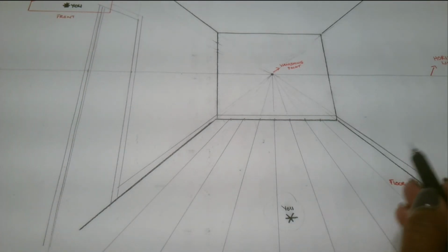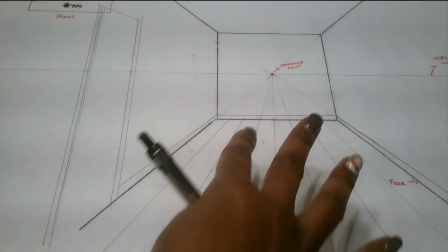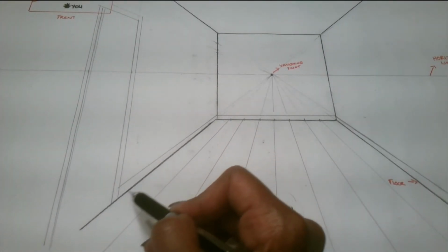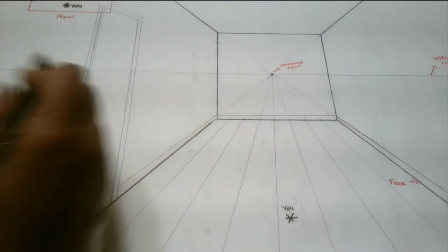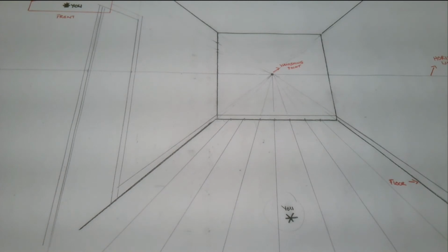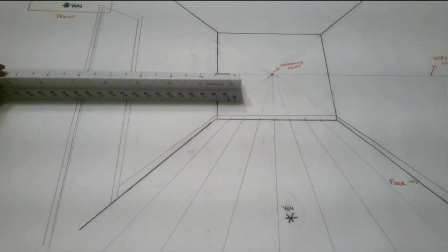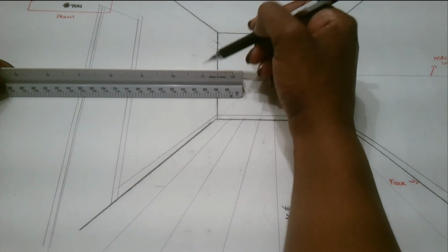If, for instance, you wanted to create tile flooring, you will go the same route as you did here, but how would you get these lines across? Would you measure here and just start drawing lines over? No, you would use your horizon line from up above. And again, you will take the measurements off of your horizon line, placing your scale there and making your marks for the measurements.